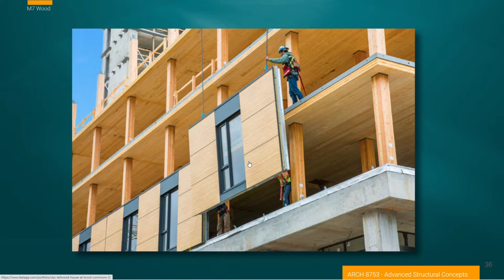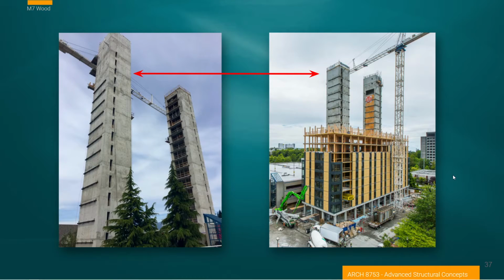exterior cladding system. And also notable is the idea that we have a concrete, usually podium or story construction. It's not uncommon in this construction to have a rigid, stiff first floor and then softer floors above that. And I believe it is to enhance seismic performance of the building.